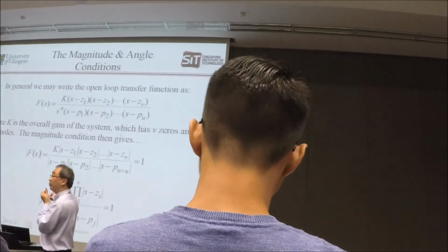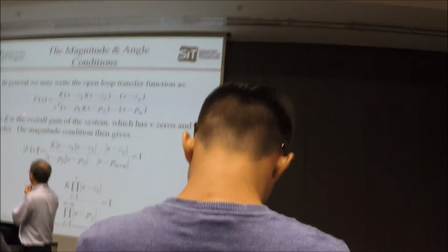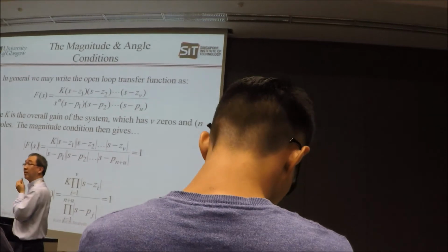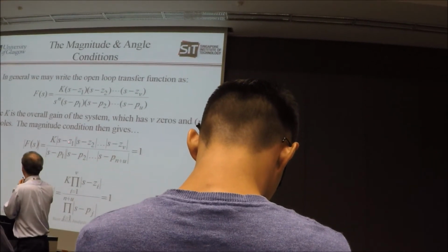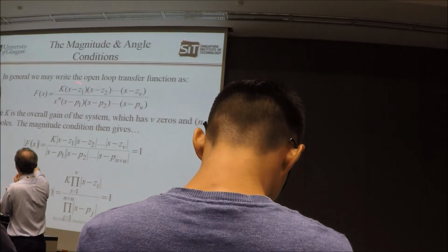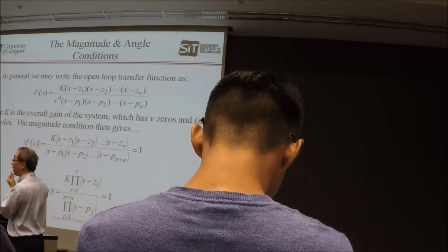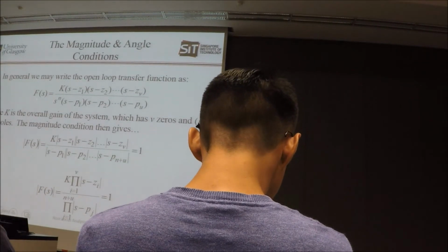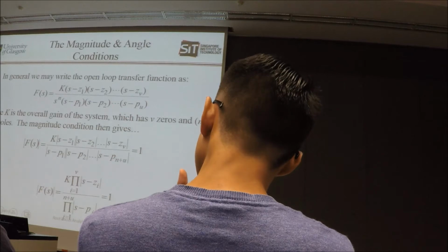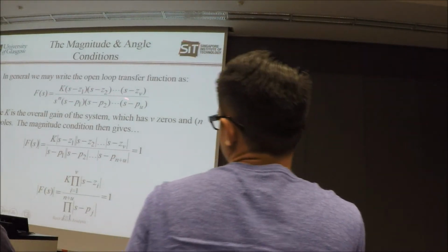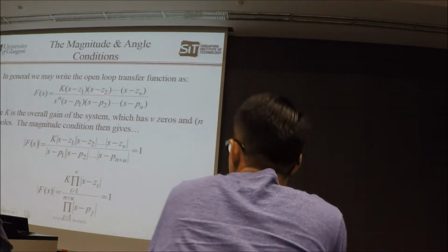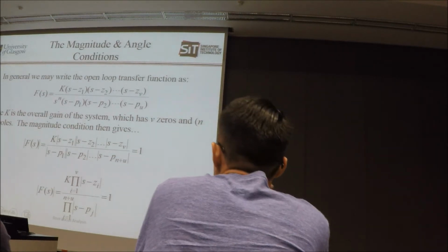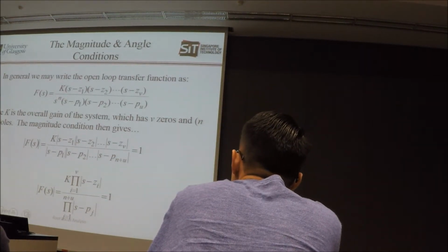If your magnitude condition basically requires F(s) equal to 1. Agree with that? Okay. So now, if your F(s) is actually being represented by orders, that means if you were to determine the magnitude of your F(s), what are you doing? You are determining individual magnitudes, your zeros, your poles, and so on. Okay, so that's what we say. If you were to determine the magnitude of your F(s), we are actually trying to determine the zeros and poles